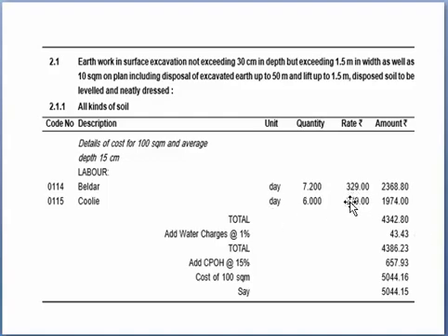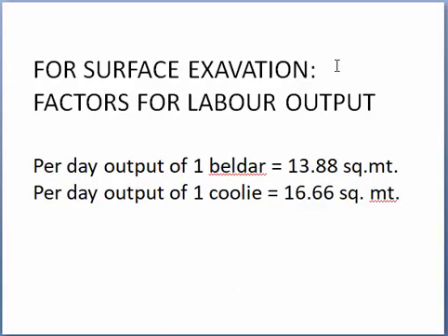Students, the unit will be day, the rate is taken from DSR, and the quantity has been calculated from the practical experience of the engineers. Earlier also I have told you the outputs have been derived from practical experience. The experienced chief engineers, the retired chief engineers, the panel, they look into the practical work done on the site, and by considering that work they calculate the various outputs, and those outputs are used in preparing these analyses of rates. For example, you can see the outputs for surface excavation.